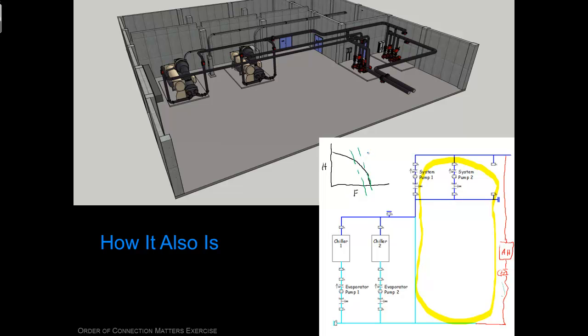moving around on the system curve for the piping system, which is a parabola that kind of looks like that. So instead of going like this to get to the reduced flow, where you wanted to end up here, the valves would shove you up the curve to get there. The variable speed drive brings you down this system curve to get to that point. I've exaggerated it in the drawing, but you can see that saves significantly more energy. So that's why it's an attractive technology.